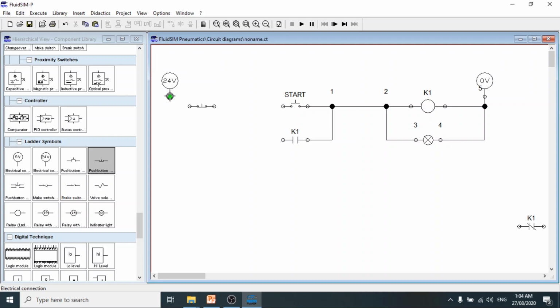In a series circuit, when one series element is damaged, everything in the series circuit will be affected. So if we put the normally closed push button in series and break the flow of current, then everything in the circuit will be turned off also.